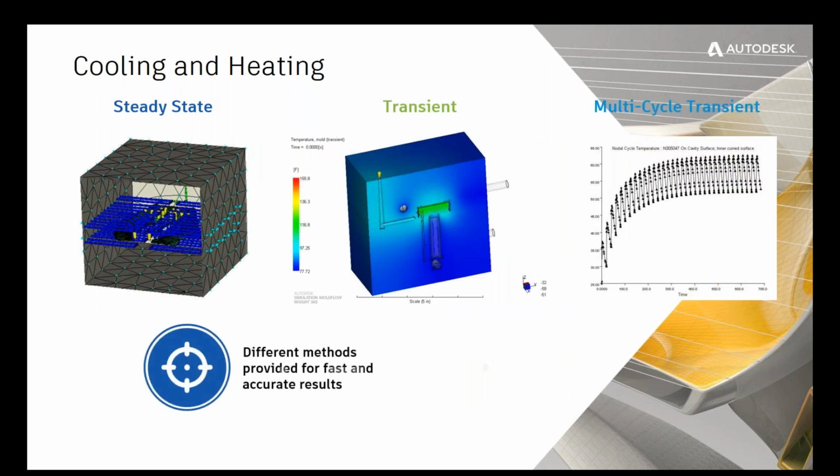There are several cooling analyses that can be evaluated in Moldflow: steady state, transient, and multi-cycle transient. Depending on the criteria will likely depend on which cooling analysis you want to run. Do you need the fine detail of startup from production, or will a steady state analysis get the job done? The more detail you're after may increase the analysis time, but imagine being able to predict how hot an insert is at a specific time and how that affects your cycle time.